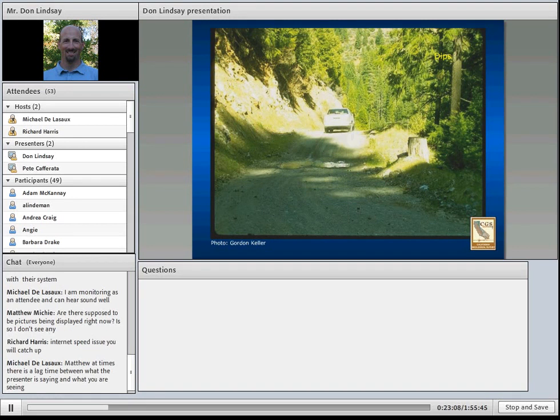Also, dips are not good on steep road grades, which I'll consider greater than 12%. This is mainly because they would require long, steep approaches.